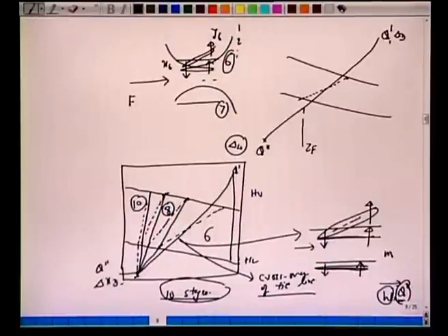All right. So that's the entry of the feed, and once we cross this feed, we are now in the stripping section. Then we connect with this, and we continue marking our data points like y1, y2, then y8, which will correspond to x8, y9, y10, x10, x9, etc.